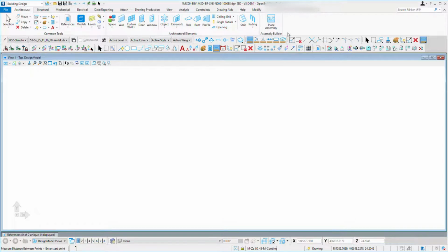So we pick minimum between, and we select highway, and we select soffit of the bridge, so it will give you that minimum distance in between. So distance command is most important, and I hope generally people are using it very frequently. Okay, so up to here I think there will be no problem, and we will continue with other things. It is a major command.